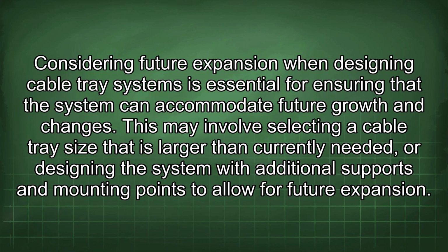Considering future expansion when designing cable tray systems is essential for ensuring that the system can accommodate future growth and changes. This may involve selecting a cable tray size that is larger than currently needed, or designing the system with additional supports and mounting points to allow for future expansion.